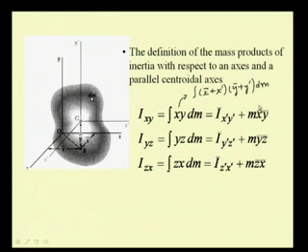One has to again remember that x bar, y bar, z bar are nothing but the coordinates of the centroid, and in the same way we have the product of inertia I z x as integral z x dm, or when we expand it in this form and simplify, we have it as I bar z prime x prime plus m times z bar x bar.